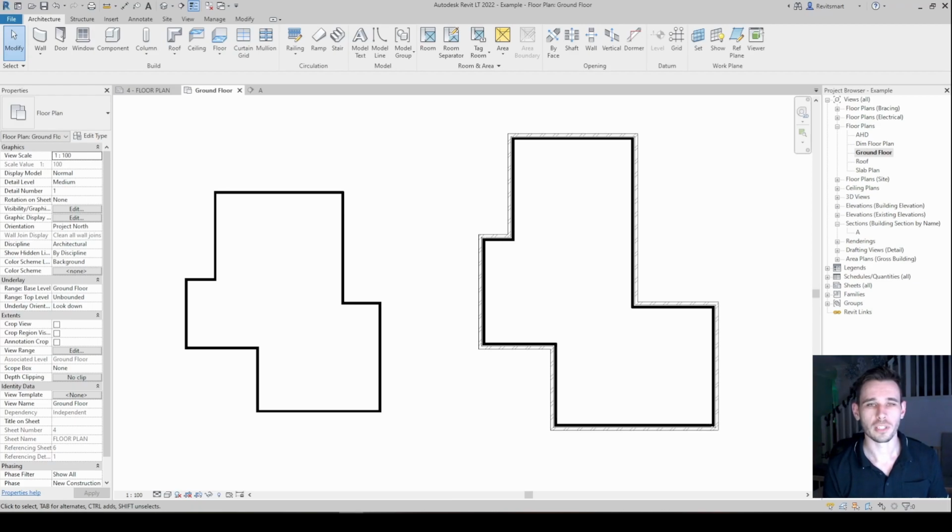Generally speaking, if you're going to be modeling the decking or the floorboards as their own floor layer and then modeling in the joists and all the bearers and the framing underneath that, that's one direction you're going to head down. Other offices, like the one that I work for, will have the floor joists and the floorboards in just the one flooring element.